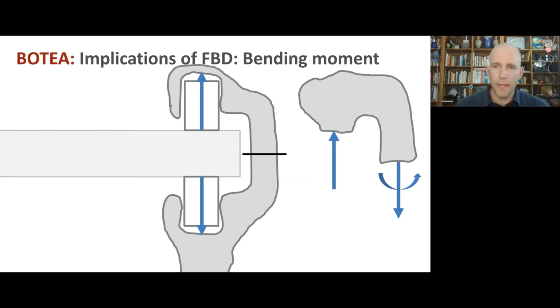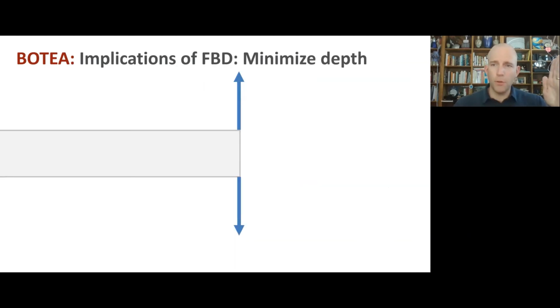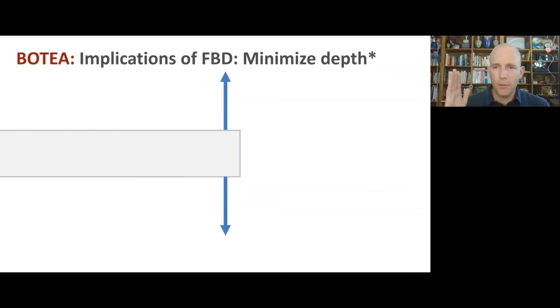So we want to keep those bending moments as small as possible. And this free body diagram tells us, therefore, that we should try to put those normal forces as close to the edge of the door as possible. Now, of course, on the other hand, if we have some infinitesimal nudge, in this case, we're going to slip off the door and fall, and that's catastrophic. So we need some factor of safety. And we'll probably want to offset these from the edge of the door by as little as we think we can get away with without slipping off the door during that